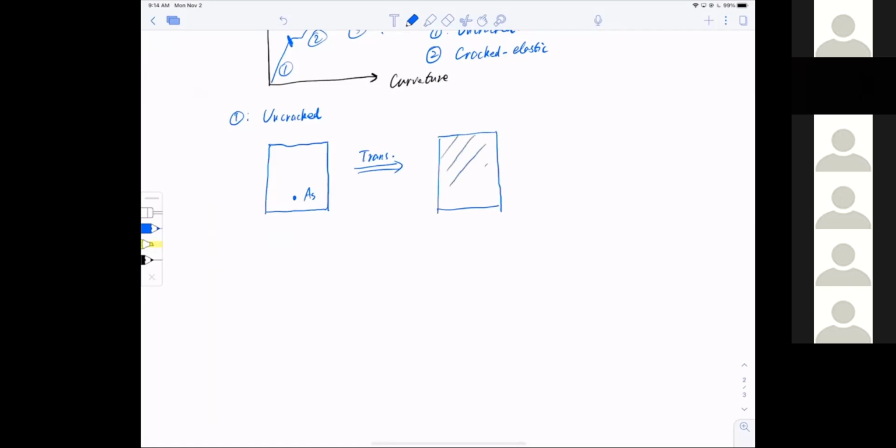This is the concrete section, filled in, with a strip sticking out that is converted from steel. So this is n-1 times AS, and n is defined as the ratio between Young's modulus of steel and Young's modulus of concrete. This is for the uncracked section, where we calculate the moment of inertia.